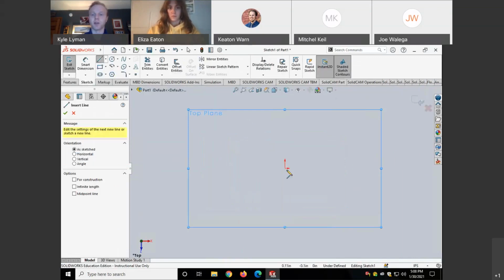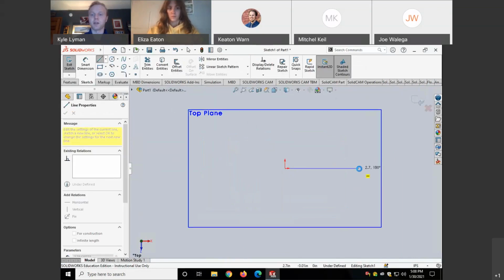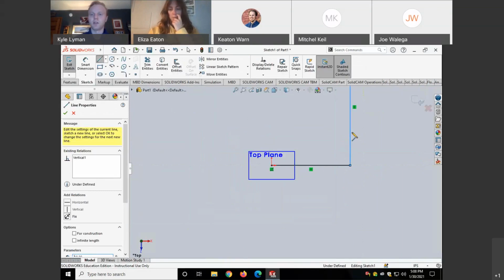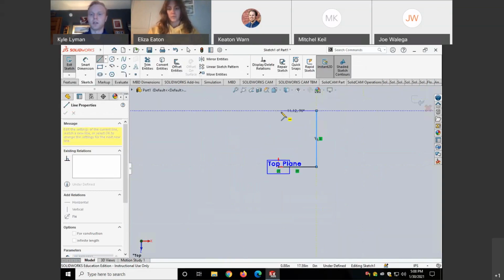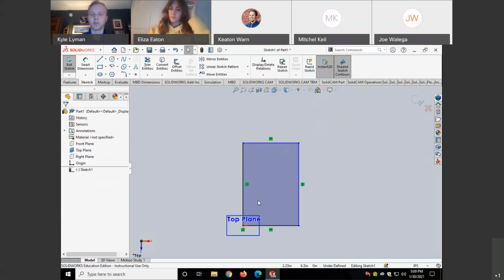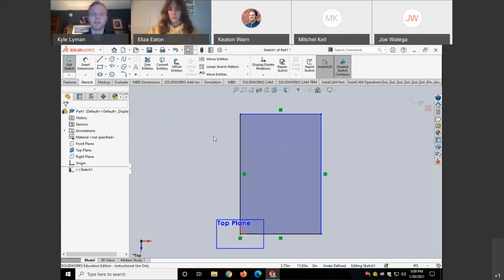I know that there is a rectangle tool, but I want to customize the size of mine. So I'm going to make this 12 inches, so 1 foot, by 1.5 feet. So we're going to do 18 inches here, and we're going to do 12 inches again. It's going to meet up there and back. And you can see it's been highlighted blue, which means it recognizes that that is a closed shape and that could be turned into a surface. If it's not highlighted blue, it means it's not closed.